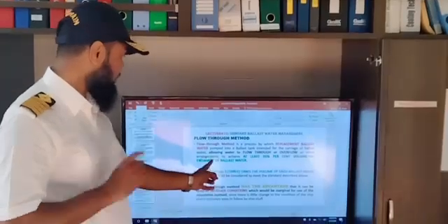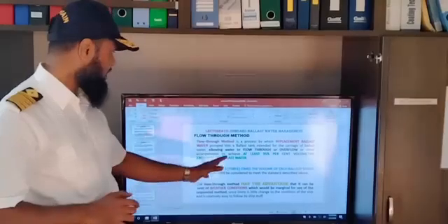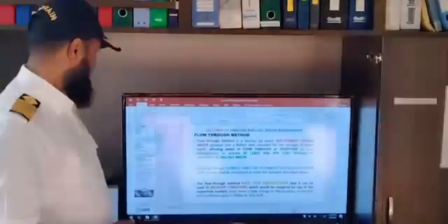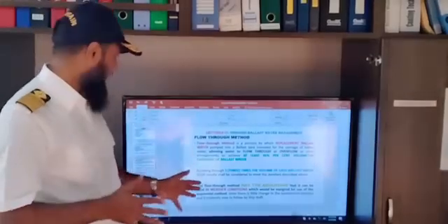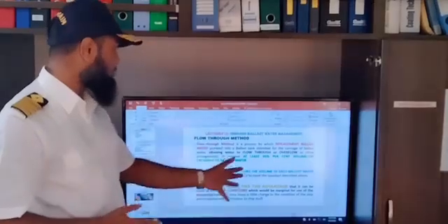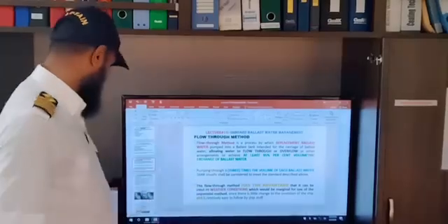Pumping through three times the volume of each ballast tank should usually be considered to meet the standard described above. The flow-through method has the advantage that it can be used in weather conditions which would be marginal for the use of the first method, the sequential method.